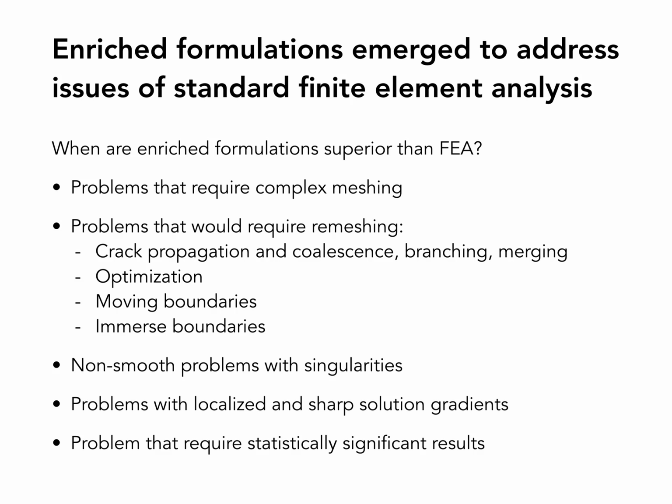If you obtain the solution to that problem, how do you know if that is the actual material? You have to come up with many realizations of what we call a periodic unit cell, or RVE, representative volume element. So you have to place or pack these particles in many different ways.